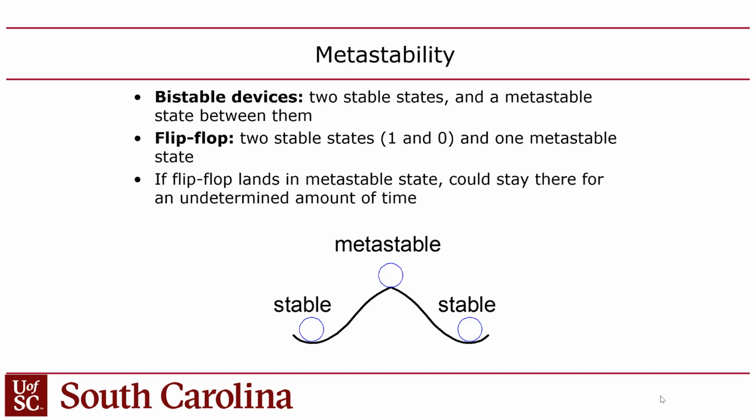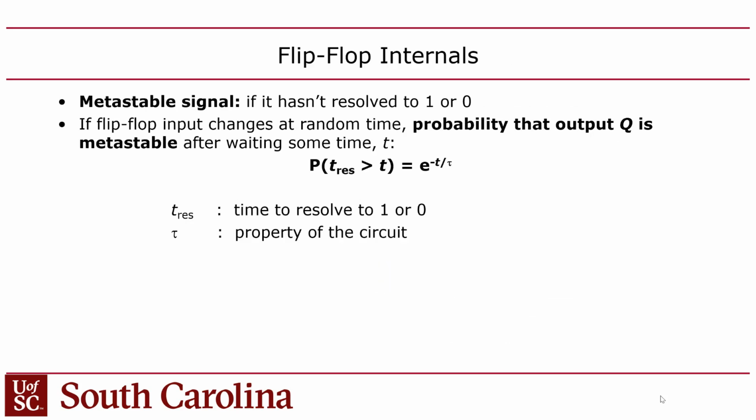So how do you deal with that? Well, there's a couple things. First of all, let's just assume for a minute that you do put a flip-flop into metastable mode. How long does it stay there? I mentioned to you that it doesn't stay in there forever. It will eventually stabilize. It just goes wonky for a while. How long is it wonky for? It turns out that the time it's wonky is based on an exponential function.